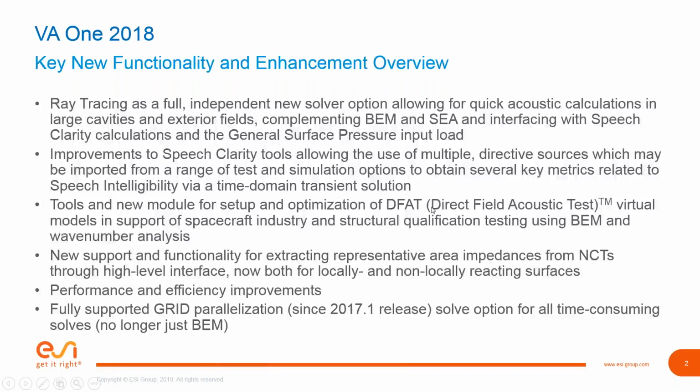The next topic is something called a DFAT, or Direct Field Acoustic Test Module. This is something a little bit specific for aerospace and the launch vehicle industry. This is a virtual test or a simulation in support of a new wave of testing being done with stacks of speakers rather than the old traditional reverberation room. Mostly they really want to establish that this type of test gives you an equivalent sound field, properly diffuse. We can use simulation, virtual testing to characterize the field and show that it's diffuse or show what kind of field you have.